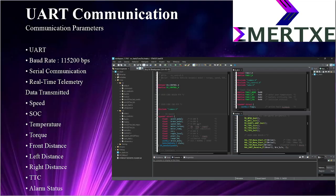Going to the next, that's the UART communication. The communication between the STM32 and the Python dashboard happens through UART. The UART baud rate is configured to be 115200 bits per second. The STM32 continuously sends vehicle parameters like speed, battery percentage, temperature, torque, and sensor distances. The Python dashboard receives these values through the virtual serial port and updates the display in real time. This communication is one of the most important parts of the project.